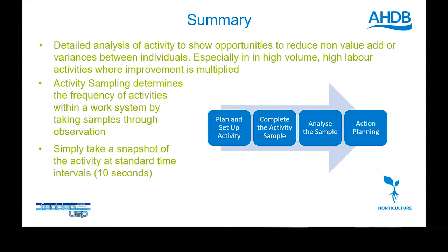You pulled out 2 points. One was confirmation bias. Just be wary of that. I've done it a few times myself where I've suspected there's too much walking in the operation, in the process, and I found myself anticipating the movements and trying to anticipate when somebody was going to start walking, and therefore skewing the results. So having two people do it is a good way of separating that confirmation bias, because you've got one person who does the observation, one person who writes it down. So that's definitely one thing I was going to bring up.